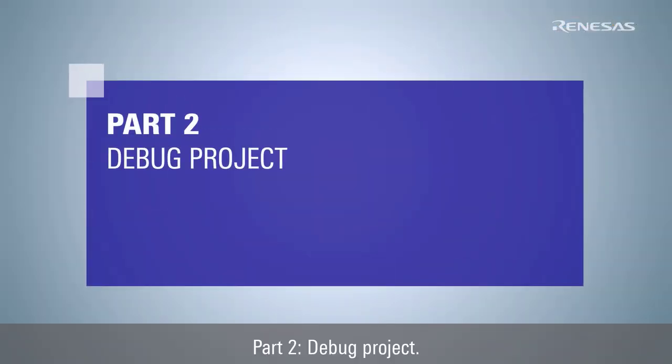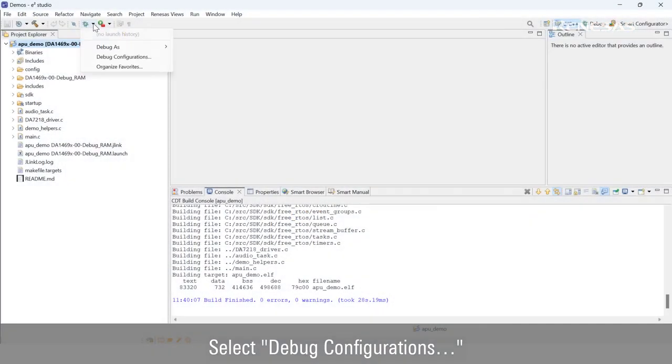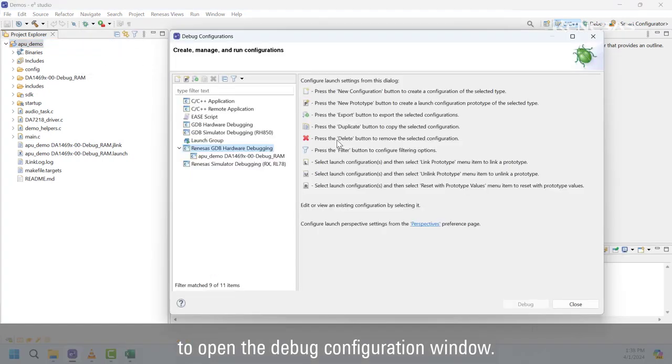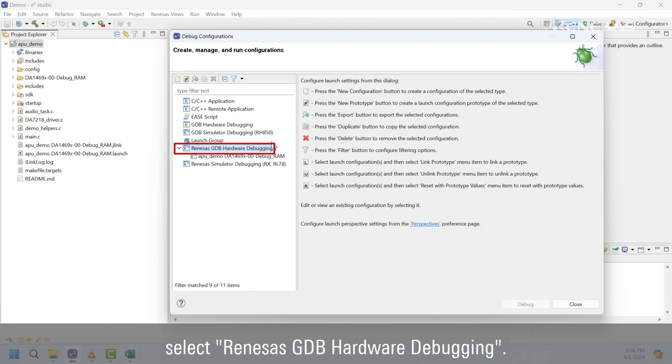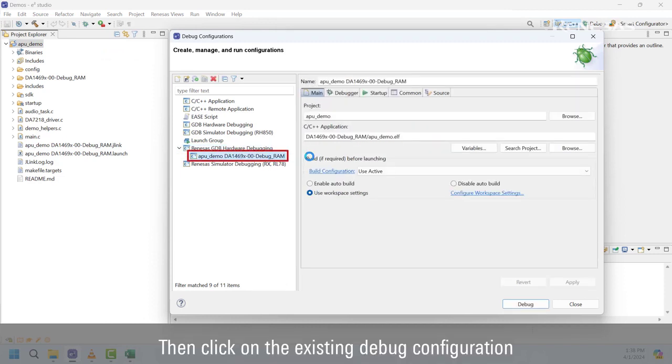Part 2. Debug project. Connect mini USB cable to the target board and the computer. Select Debug Configurations to open the Debug Configuration window. In Debug Configurations window, select Renesas GDB Hardware Debugging. Then click on the existing debug configuration.